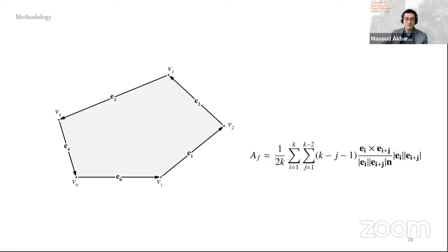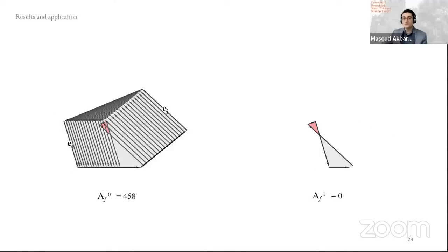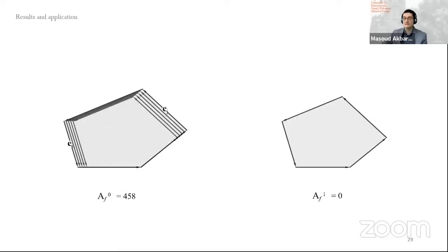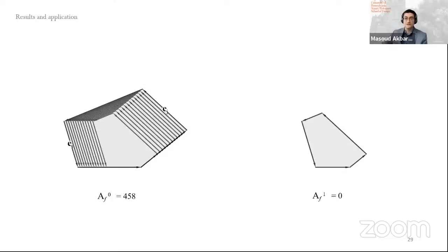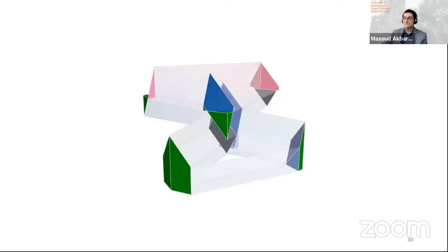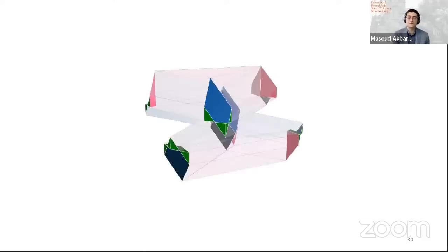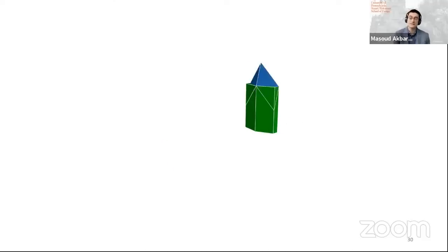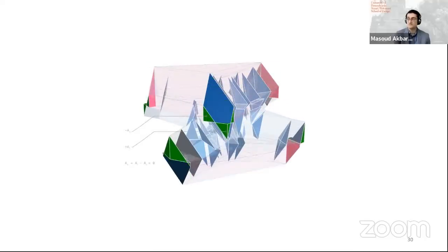For this reason, we developed a quadratic definition of the problem to control the areas of self-intersecting faces. And then we were able not only to control the area, but to make certain applied loads disappear from the definition of the problem. As a result, we were able to create distributions of forces with really well-controlled boundary conditions, and to remove certain horizontal forces in the boundary condition using geometric techniques, right?